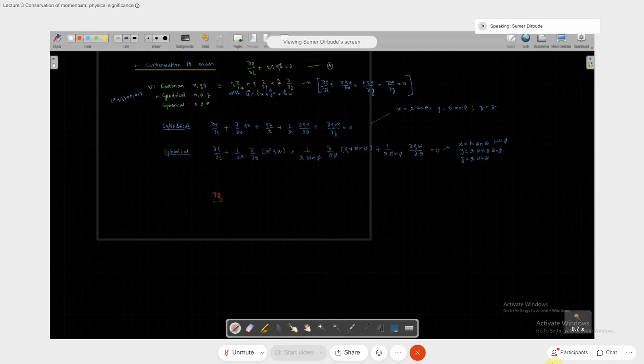So, ∂ρ/∂t, the first term, shows what the change of ρ in a system is with time, locally. If there is an addition of mass or some mass source, happening over a period of time, then it will be reported in this term. So this is a local rate of change.